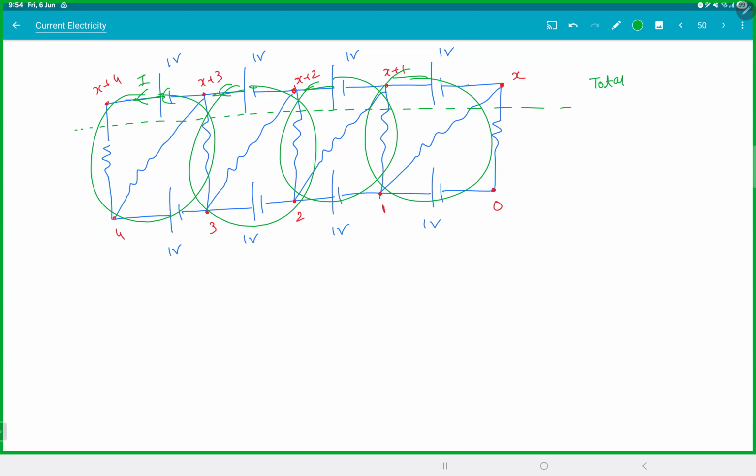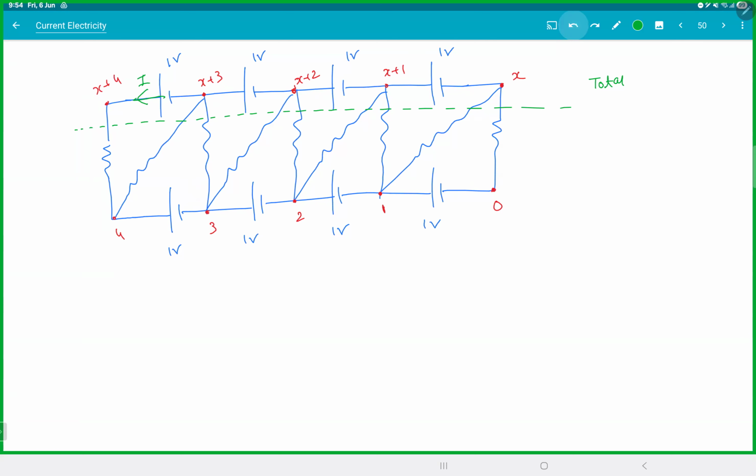So junction law, right? You can apply it for multiple junctions at the same time. I'll show you an even better way to figure this out, but this idea is clear. That's a pretty good theoretical question actually. If a line is drawn through a circuit, the net current crossing any random line in a circuit is 0. And all this works because every battery, whatever it sends, has to come back. So the total current crossing the line has to be 0.